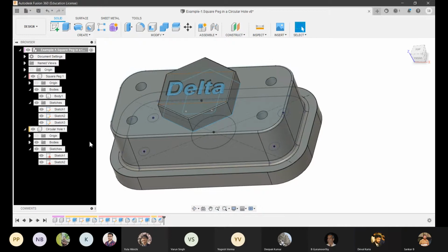It's because in terms of manipulation later on, if you want to change the values or do anything else, you need to go back. Let's say if I want to remove the sketch now, you'll have to delete that sketch element and then join the lines again, or if the dependencies break, you'll have to give the constraints again, right? So in terms of the work required to do any changes, it's much more intensive when you give a fillet within the sketch. But if you do it with an operation, like we had discussed, then it's easier because you can add multiple fillets within the same feature, right?